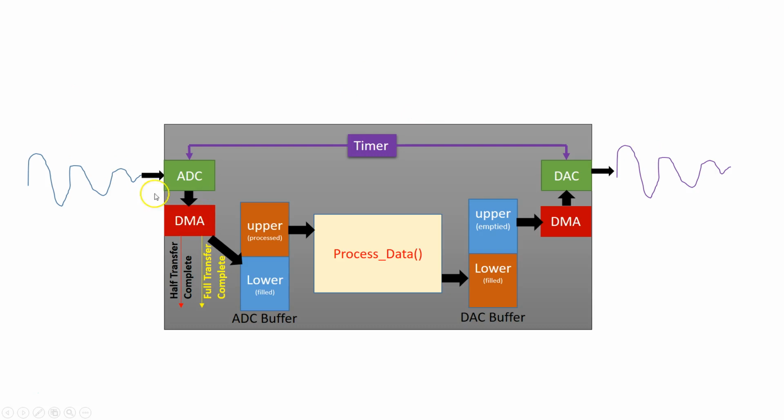We'll set up ADC 1 channel. In the Nucleo board, I want to put in my data going into port A0 in the CN9 connector. So port A0 in the CN9 connector belongs to ADC 1, 2, and 3. There are 3 separate ADCs, but it belongs to ADC 1, 2, 3 channel number 3. Again, there are a lot more channels than just 3 here, but I just show you a snippet of that. So ADC1 channel 3 will be our ADC, this particular ADC hardware.